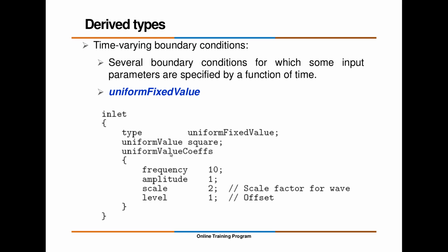So here we have a square type of wave, or this way you can specify different things. Okay, so time varying boundary conditions has certain options. But I normally don't go with these options. If I want to specify a time varying equation or something, then either we go with the groovyBC type of condition that is available in swak4Foam, or the best part is to code our own boundary condition and go ahead. With the help of that we have proper flexibility to control our own way of inflow, outflow, or whatever the dependent variable, how you want to vary everything.